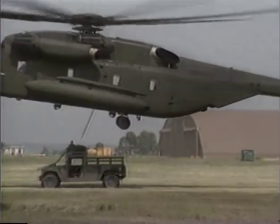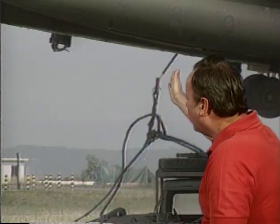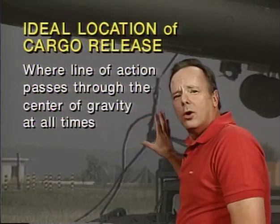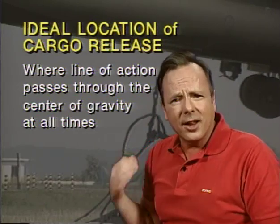Well, one of the neat things you can do with a helicopter is pick up external loads. Now, would you say a truck qualifies as an external load? You bet it does. And if you want to pick up something like this, you'd like to locate this cargo release and the hook at the best location. Now, where is the ideal location of the cargo release? Well, how about where the line of action passes through the center of gravity at all times? That way you won't be making wild changes in the center of gravity of that helicopter when you pick something up or release it.